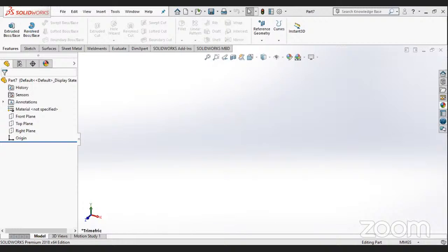We'll start quickly drawing from the front view. To make any model, you will get this sheet which is called a drafting sheet. On this you have all the views, cut section views and detailed views for the dimensions of whatever model you are going to make. This is the front view, this one is the top view, this is your side view, and the section which is written here, cut section from A to A, means this is your A, this one is your A. So this is the cut section in between this.